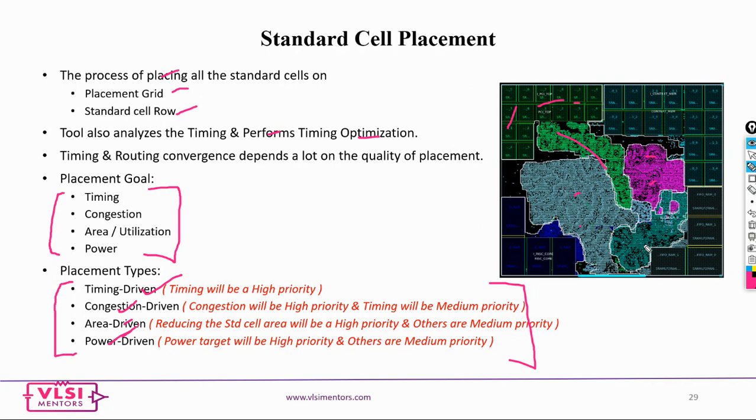All the standard cells are placed, and you look at this green color. So these green color macros are talking to this green color logic, so they are all pulled close by. And the next one is this blue color macros that are talking to these cells. So they are eventually pulled closer. So your floor plan drives your placement also, remember this. If you get your floor plan right, as I said, your 60 70% of work is done.